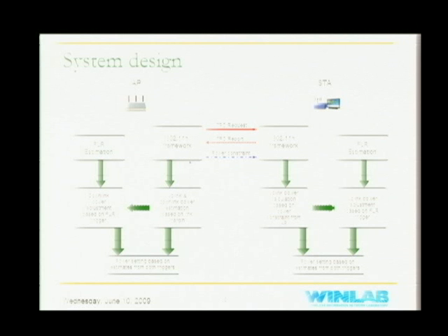Here we calculate the transmit power purely based on link quality measurements. There is also simultaneous frame loss rate estimation going on in the transmit path at each transmitter. And then the power estimation based on link margin block provides the basic transmit power for adjustment here.